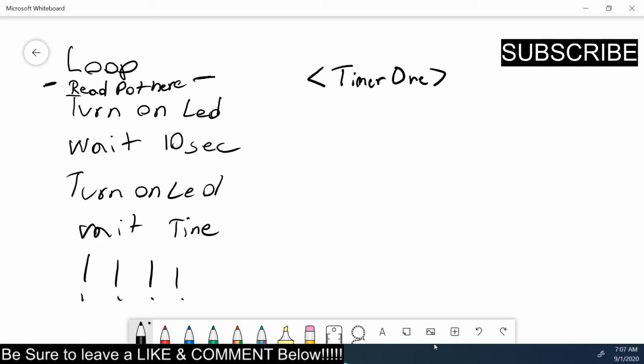So you'd have to do pound include, and you put the Timer 1 library in. Oh, it's .h. Let me put that in correctly. .h, and you put that at the top of your program, no semicolon, and then you may have to download the library. I will show you how that is done, but this basically gives you a software interrupt, and what you do is you will set up your Timer 1.